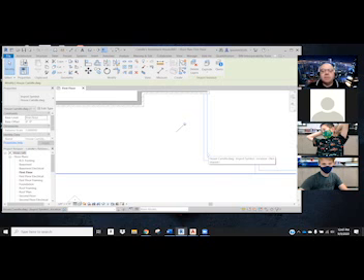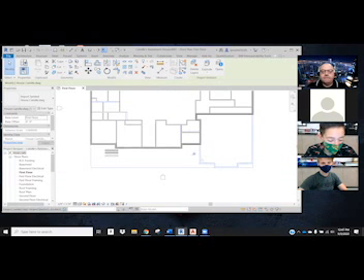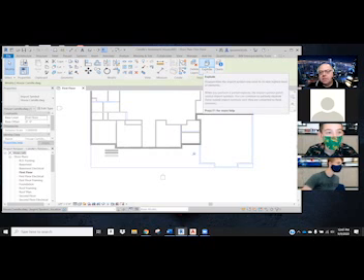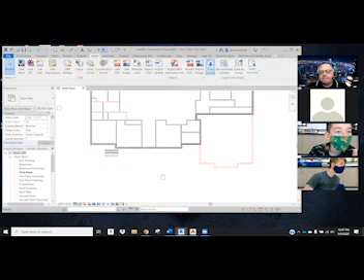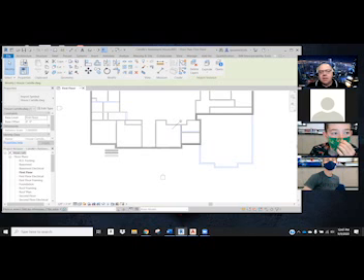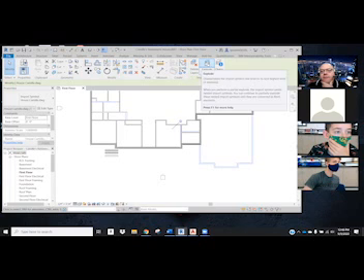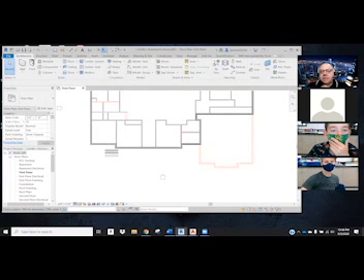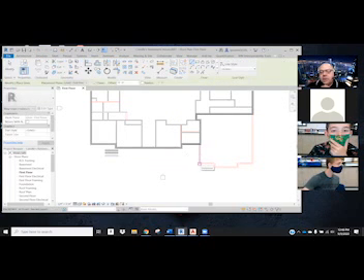Okay, we're going to try something that's going to be a little bit of work later on for us. You ready, Sam? This is a tricky one. Go ahead and select your AutoCAD file so it selects the whole thing. When you do that, it's going to jump you into the Modify tab, and there's one that says Explode. Go ahead and hit the Explode button. I'm not done on mine because I just exploded it. So you select it once, you see the pin, then you're in the Modify tab, and there's Explode. Okay, try that. Then go back to Architecture and the model line and see if that will grab it now.